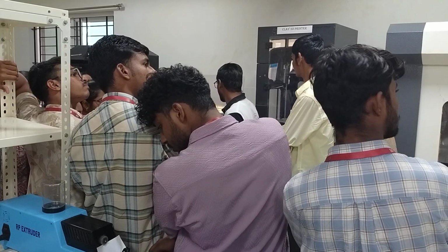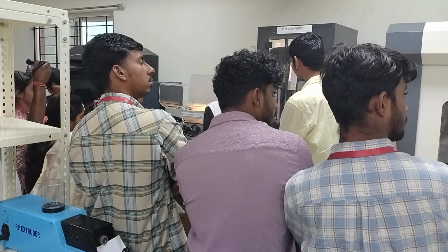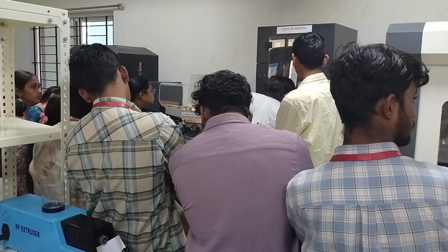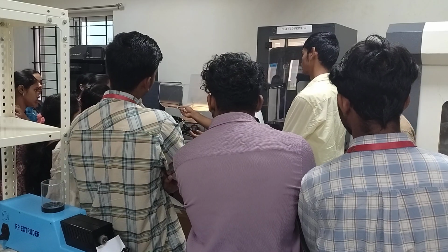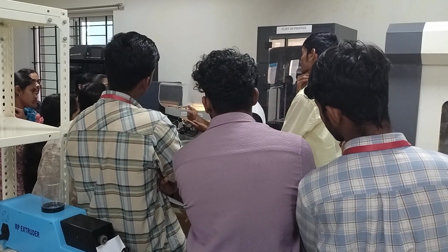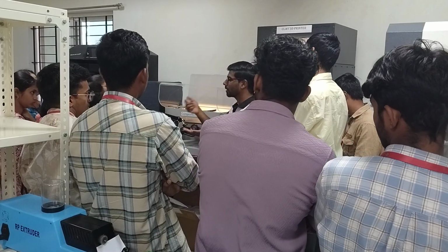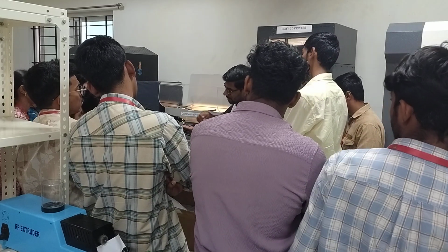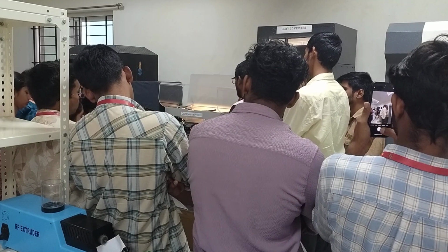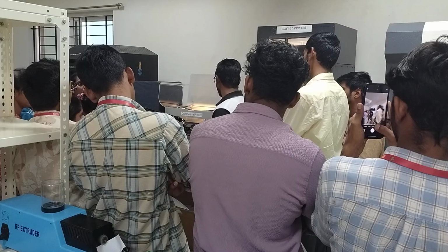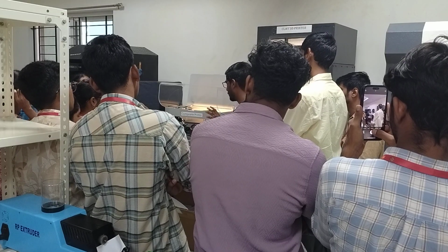So it is running a purge line. So I think this is one thing that you want to see, that purge is happening. Yesterday I had printed some parts. Purging is actually when some of the filament is stuck here, or the filament is not reaching up to the nozzle and we start printing, it may start printing air and the print may not come out properly. So we deposit extra material on the bed to make sure that the purging is happening properly, the temperature is proper and deposition is good enough. That's why it deposits some extra layer before printing. So that is called purging.